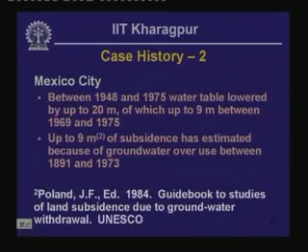However, many apartment buildings in the city of Calcutta draw groundwater by installing deep water wells within the property limit of the apartment. So, in many areas, high-rise apartments suffer from differential settlement leading to cracking of masonry infill walls within the reinforced cement concrete frames. This is a real problem in the city of Calcutta, but the problem is more remarkable in another case history involving the capital city of Mexico.